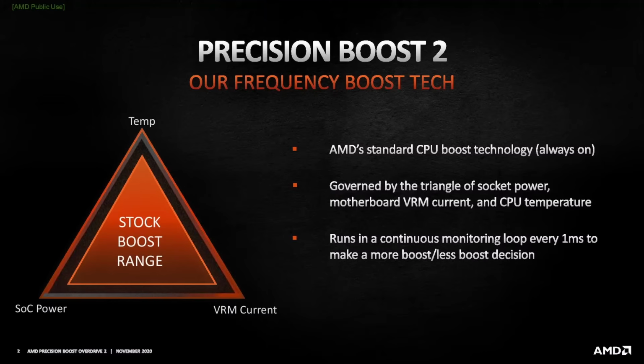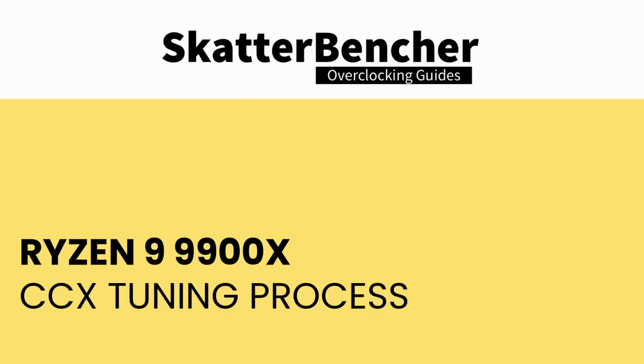That means the CPU is no longer regulating the load line itself, and instead we have to correctly configure it ourselves. Choosing the proper manual voltage for our manual overclock is always going to be a trade-off between increasing the overclocking headroom, dealing with the thermal challenges that come with elevated voltages, and consideration of the CPU lifespan.